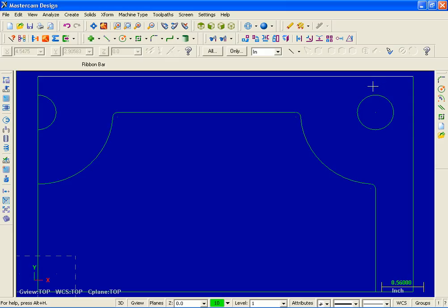What I'd like to do now is delete the left vertical line and this bottom horizontal line. So I'm going to click the bottom horizontal and click on the left vertical, and then move up to the toolbar at the top and select delete entities, and they've gone.